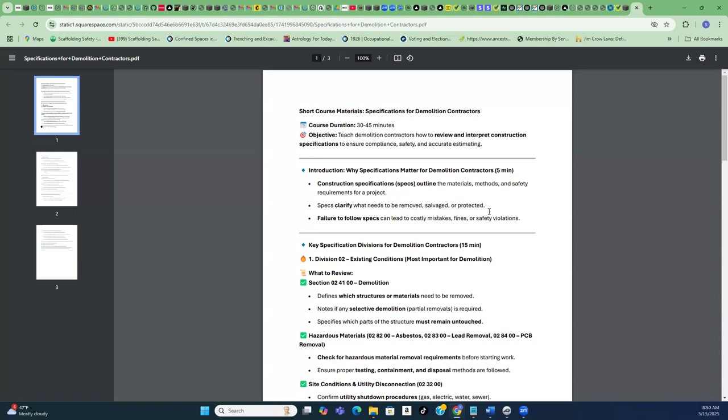It sounds like you've done interior selective demolition before. I think I have this Diablo Valley College one that we're going to look at. They are completely knocking down a building and then adding on to it. So when it comes to interior demolition, the specifications are really going to outline everything.